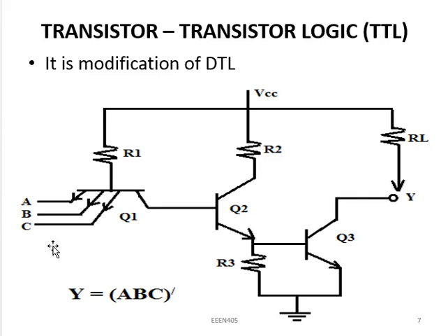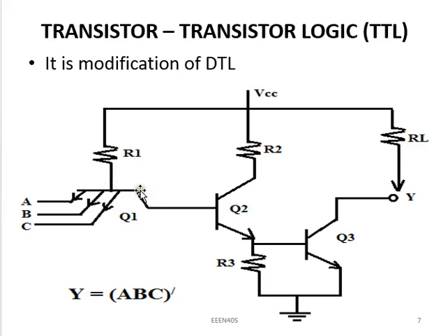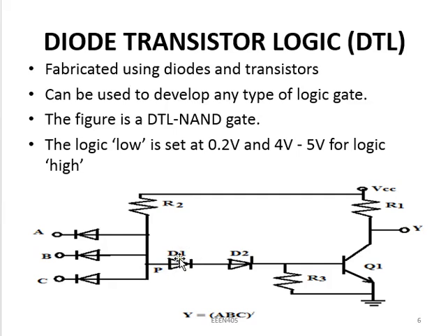And we remember that between the base and the emitter of any transistor, we have a PN junction diode. So therefore, between this base and the emitter number 1 is PN junction diode 1, and between this base and the second emitter another PN junction, between the base and this emitter another PN junction. Therefore, these 3 emitters and the base give us the 3 diodes we have here. And then between the same base and the collector is a PN junction diode, which is standing for this D1.